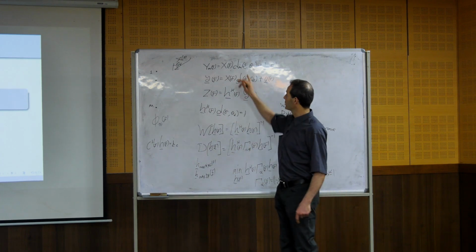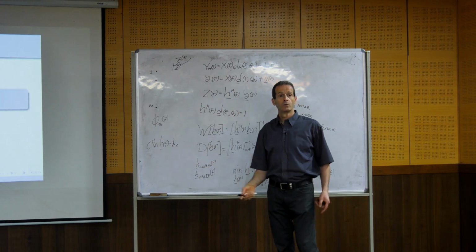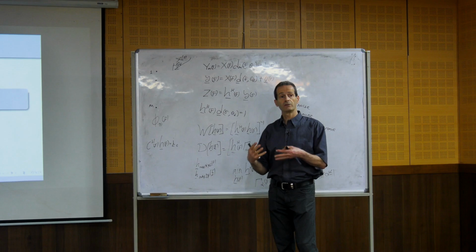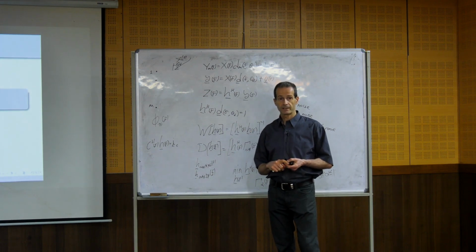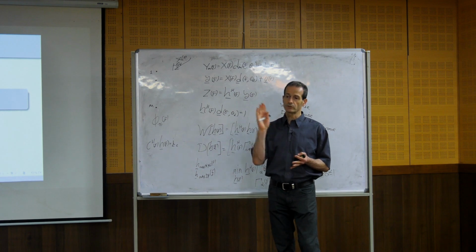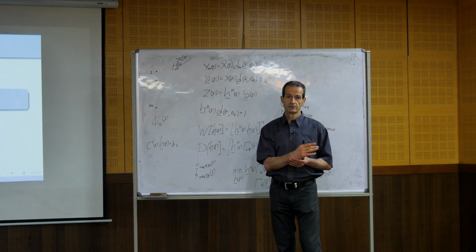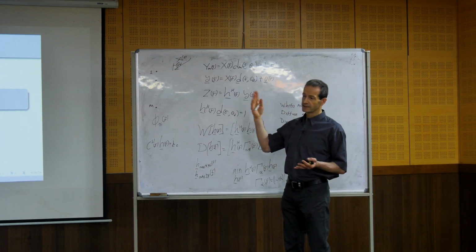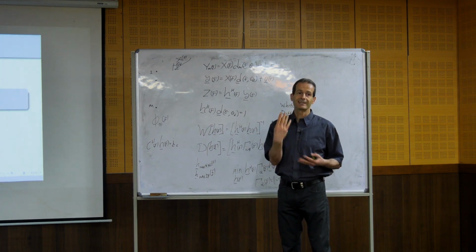And then because we work with directions instead of relative transfer functions, we can explore how the beam patterns look. Okay? Because the beam pattern takes into account directions, responses to directions. With multi-channel signal enhancement, we work with relative transfer functions, so directions are less important.